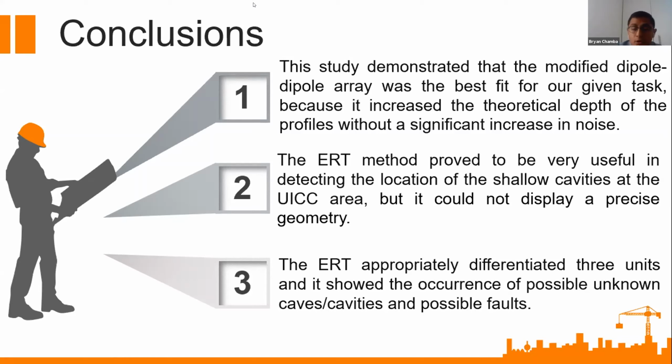And finally, the electrical resistivity tomography appropriately differentiates 3 units, and it showed the occurrence of possible unknown caves and cavities and possible faults.